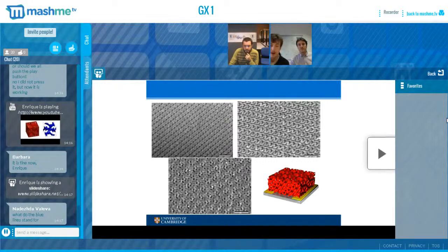And around it are images that we've taken using the electron microscope. As Mike said before, you don't see any color on these. They're just grayscale because you're just detecting the electrons. They have wavelengths, but you can't really distinguish them. So you only see how many electrons are reflected to the detector. If a lot of electrons are reflected, you get a white spot, and if fewer electrons are reflected, you get a darker spot.